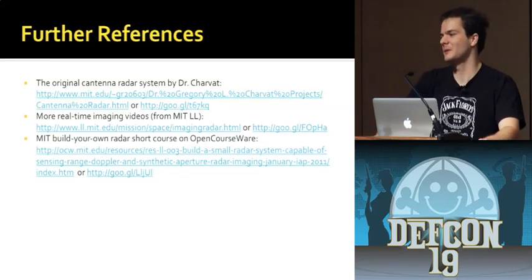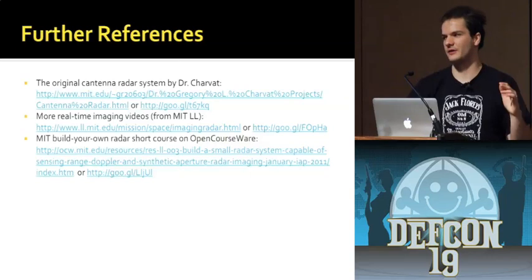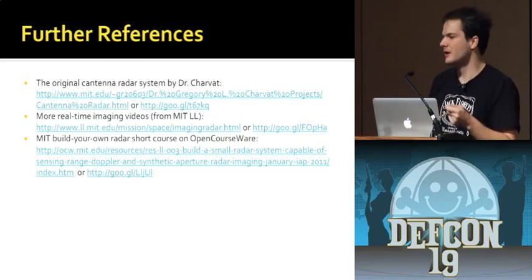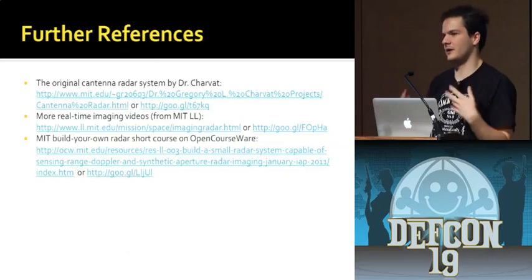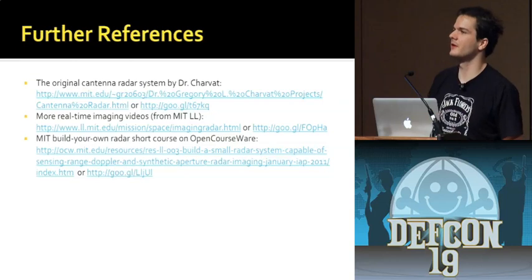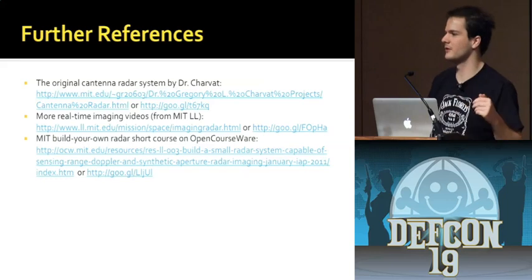On that microcontroller, it would be pretty hard. The processing power on this thing is pretty weak. It's useful for quickly grabbing data. If you switch to a DSP or a nice ARM, or an FPGA would probably be the best option in that regard, you could definitely do that. It's not a very computationally intensive process. I mean, this is a Python script I was running to do the FFT.